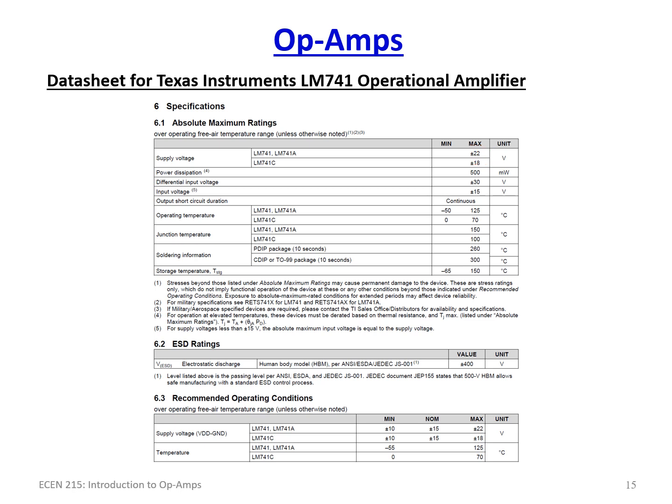And with the C, you're limited to plus or minus 18 volts for the supply voltages. It can handle a power dissipation of up to 500 milliwatts, and you got to pay attention to that. And the max differential voltage is limited to plus or minus 30 volts.